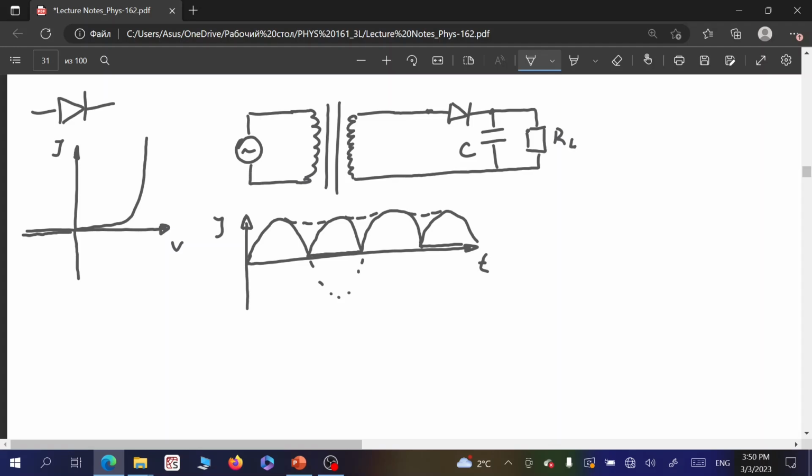Also, we highlighted this feature of the equivalent resistance for primary coil when we know the load resistance of the secondary coil, and of course N1 and N2, which stand for number of turns for primary and secondary coils. And we considered rectifiers, which allow us to go from AC current to DC current, because that is what actually happens quite often when we operate our devices.